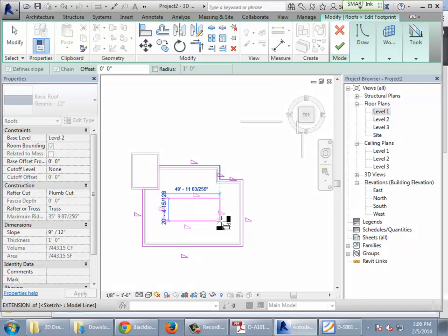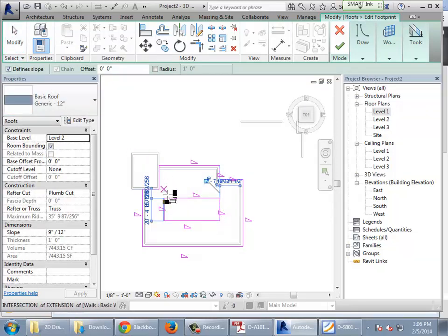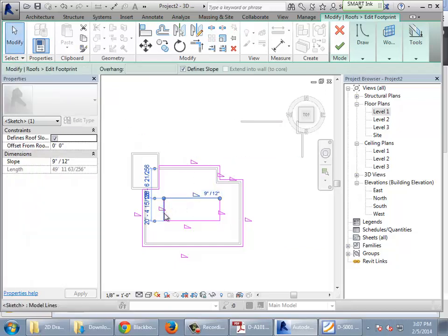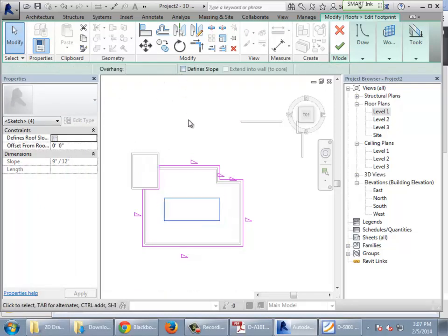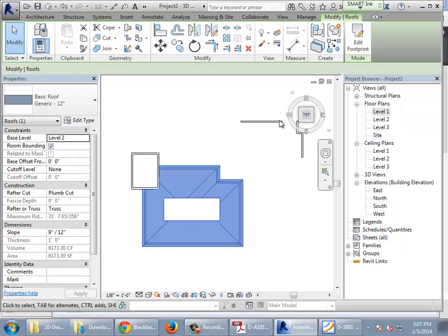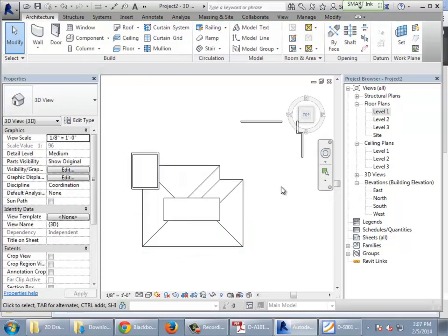like that, okay, and again, I'm going to turn off slope defining. If I did it like this, it'd be like a donut where it would come up from both sides because both sides are indicated as the bottom of a slope, and that's not what I want. So what I'm going to do is grab these 4 edges. I'm going to Control-click to grab them all. And I will say turn off define slope. Okay, there's my hole in my roof. So that's not so bad.